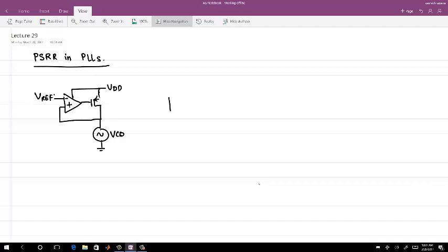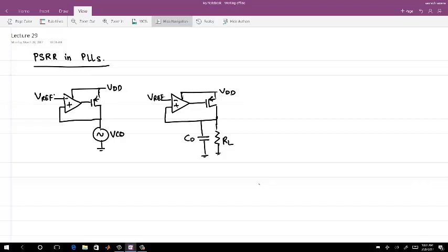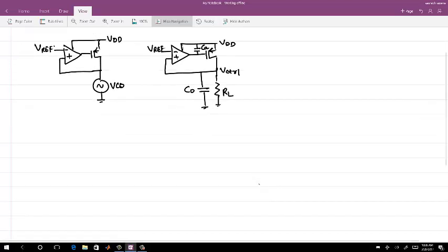So what we did was we replaced the VCO with an effective impedance, and that is to find the transfer function from VDD to Vout. So this is RL, Vref, and VDD, with minus and plus at the amplifier input, and then you have a certain output load cap Cout, and you have some cap here, CA, at the amplifier. Okay, so this is Vcontrol, and at the end we found that Vcontrol by VDD.